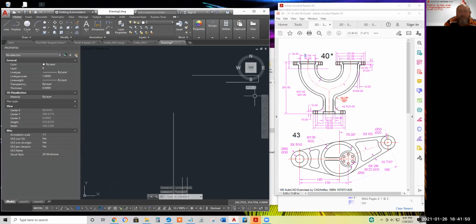Okay, starting at the middle, I'll draw a 66 unit line, and snap it to the midpoint. Move it, enter. Select, enter. And we'll draw some lines straight down. The depth of this guy is 10.